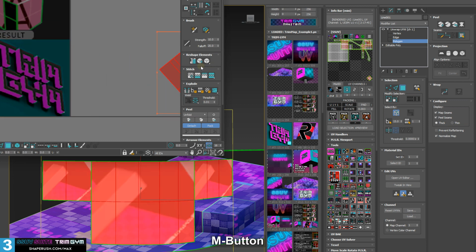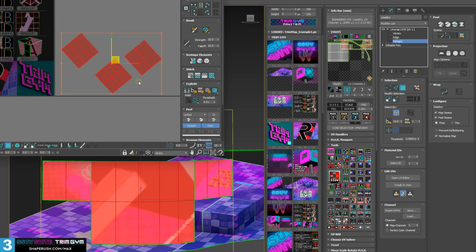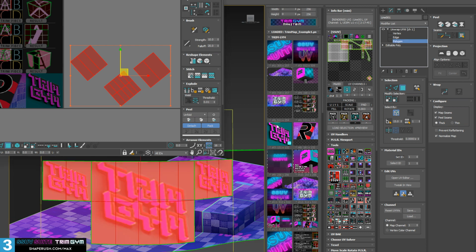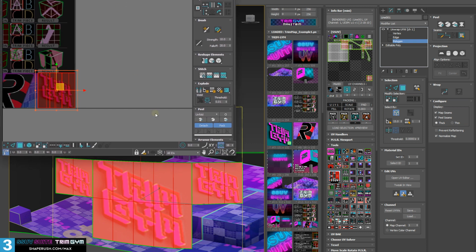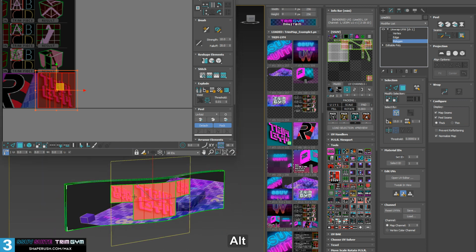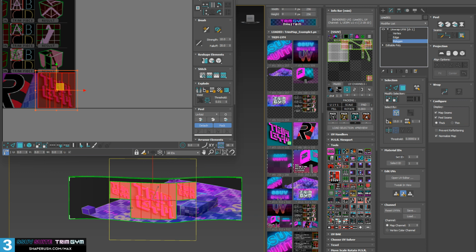Okay, so we're going to go back to that again, but we're going to select all of this and shift left click, and now it's going to try to write itself and then apply its dimensions to that element, right? We're putting the element to the dimensions of the trim piece. And that's how that works. So this will iterate through your selections if you have shift left click, and it will also iterate through on a single click, left click.